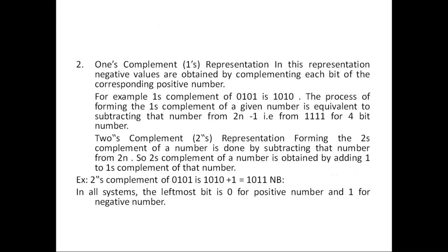Okay. Then we are using the 2's complement. 2's complement, you are already acquainted with from DLD. So first we make the 1's complement. Some number is there, say for example 0101. What is the complement of that one? It becomes 1010. Okay, this is the 1's complement. Then you just add 1 to that, then it becomes 1011. Right. So this becomes the 2's complement.